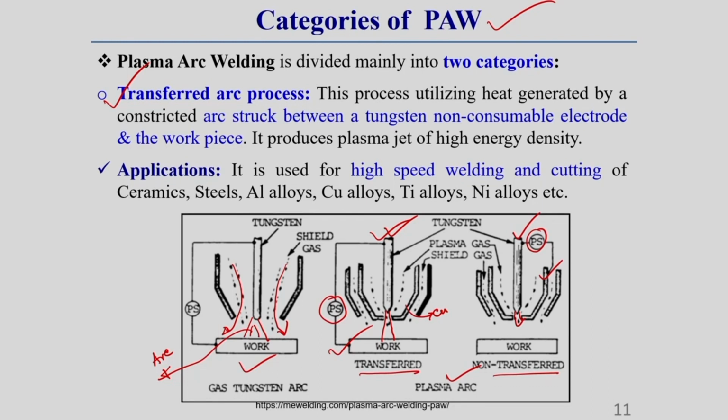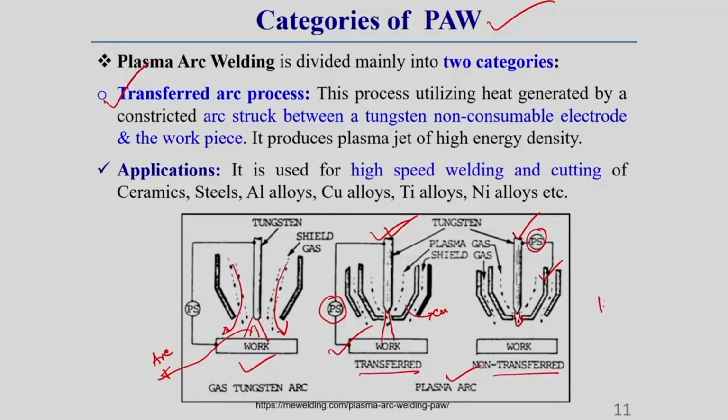and what happens, here the power density is increased, because as the arc constricts, the same power is applied over a lesser cross-sectional area. That means spot size reduces. So, what we know, same power, let this power be W, and the arc spot size be A. If this A is reduced, that means once the arc constricts, then A decreases. So A decreasing means the arc intensity, which is arc power per square millimeter, increases, as the area is decreasing. What I am telling, understand?